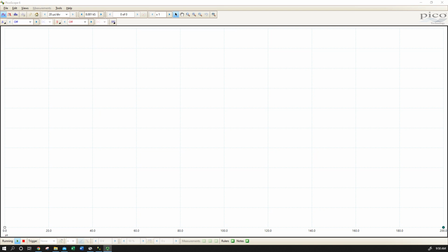Okay, as promised, I am back showing my Picoscope display. At this point, I have my Picoscope turned on, but I have not enabled either one of the measurement channels, so we're not seeing anything. They're both turned off. And as I said earlier, when I was displaying my SMath sheet, I'm using a 2.2 nanofarad capacitor in series with a 100 millihenry or 0.1 Henry inductor, and I am going to power those using a sinusoidal voltage signal from my arbitrary waveform generator here.